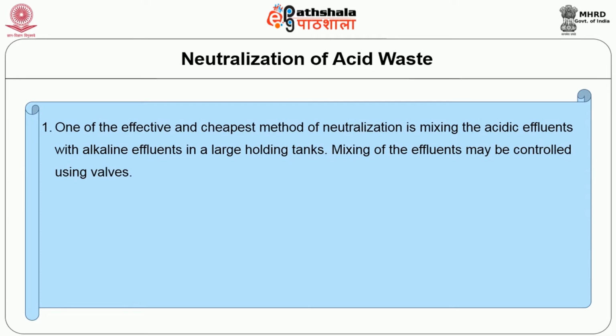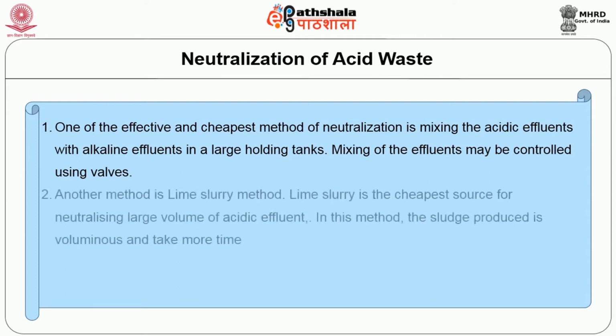First, we will see how acidic effluents are neutralized. One of the effective and cheapest methods of neutralization is mixing the acidic effluent with alkaline effluents in large holding tanks. Mixing of the effluents may be controlled using valves.